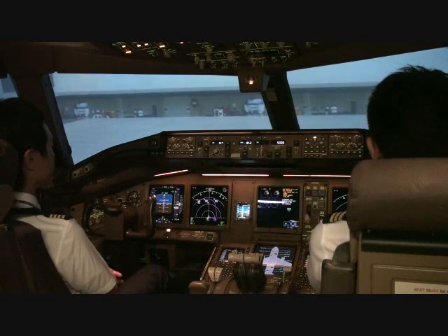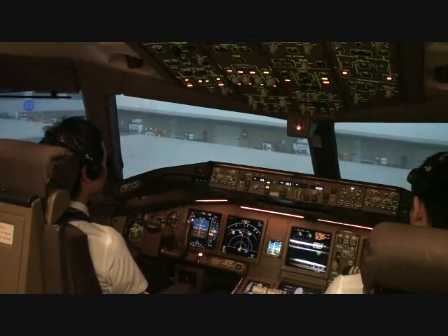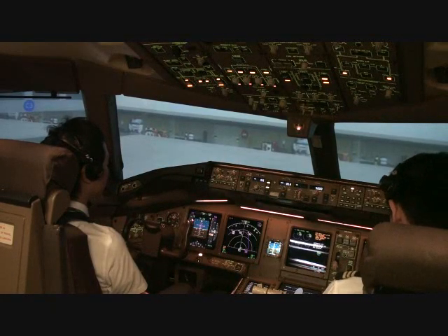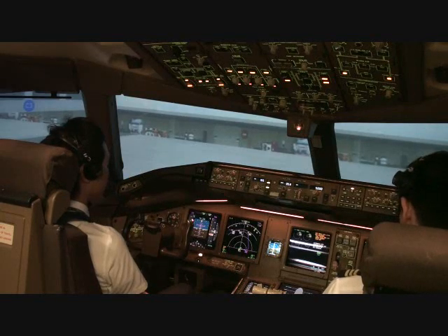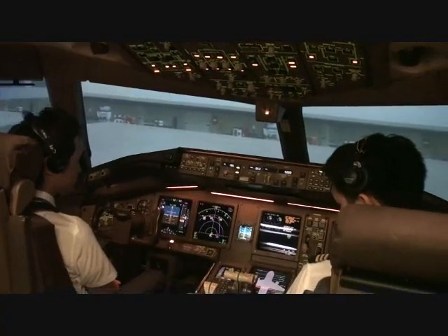Before the load and trim sheet arrives, we have the items departure briefing, fuel quantity checking, flight and maintenance log completion, and the ATC clearance that can be done in any sequence on an opportunity basis. After papers are on board, flight deck door closed and locked by CM2. Verify that the lock fail light is extinguished.